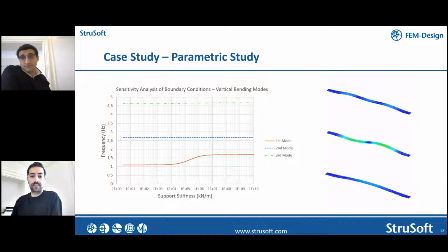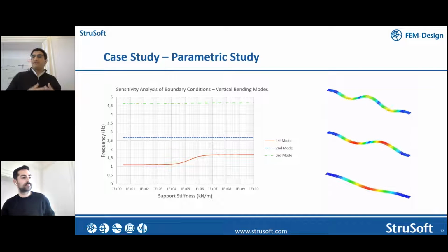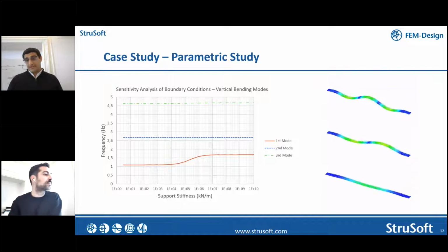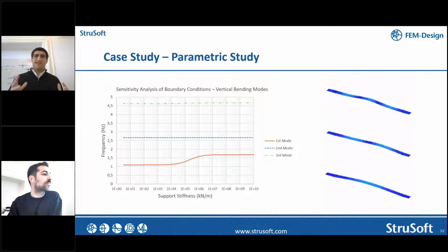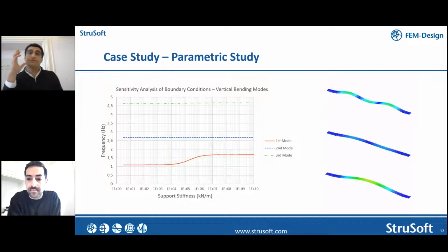Especially for the first mode of operation, you can see that when it arrives at the boundary conditions, it is actually far away from a simple support, and behaves more like a clamp from the mode shape perspective. That is something you can see in the first, the second, and the third mode of operation. And this is telling you what your reference model is closest to in your actual problem.